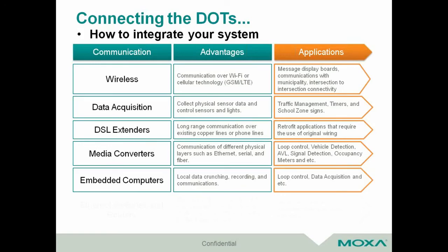Let's say, for example, you have devices out in the field, controllers that use Modbus or some sort of protocol. You can have the transparent bridge filter out specific protocols so they don't get pushed up onto your Ethernet backbone, or so you don't have someone writing into your device and making changes because someone at the central location doesn't know what he's doing. You can filter this using that, and that's what I mean.